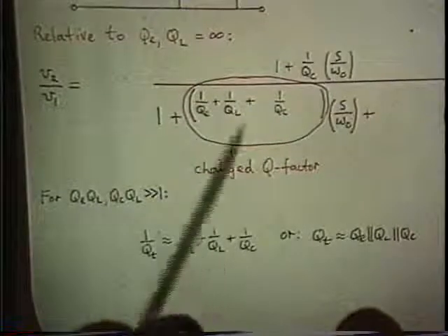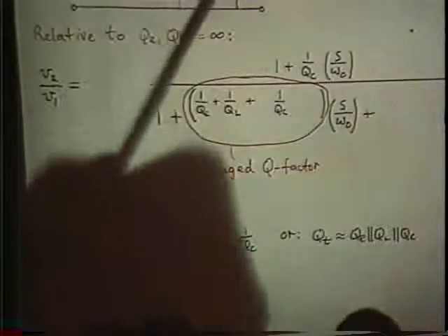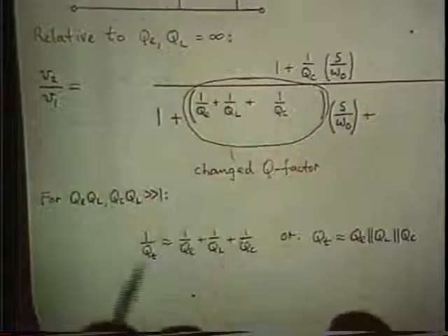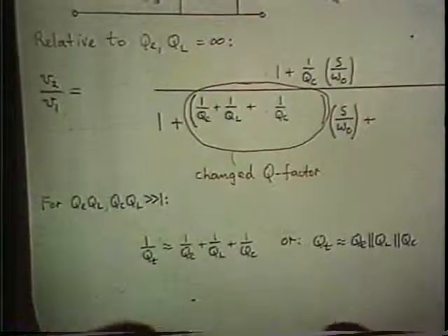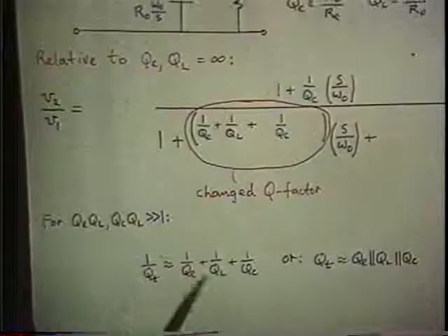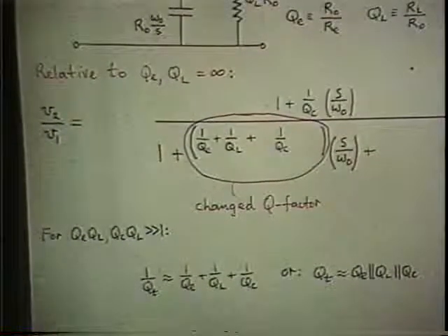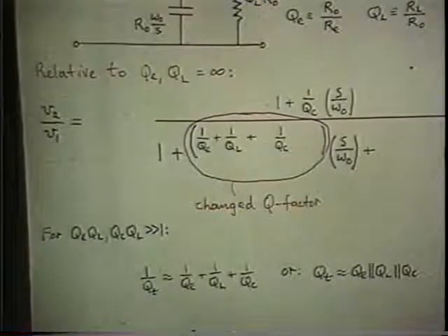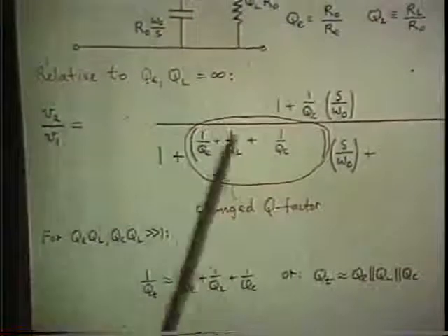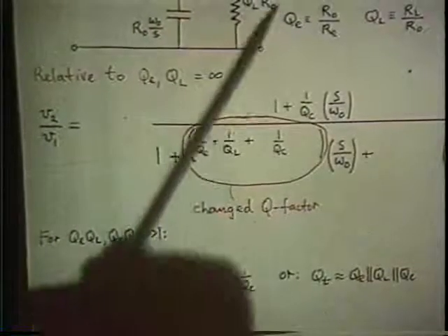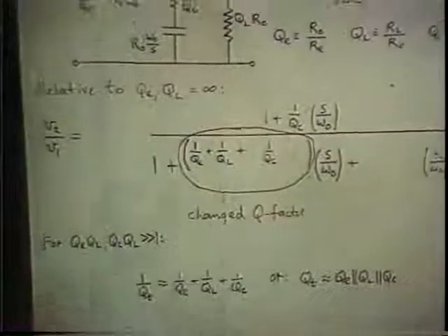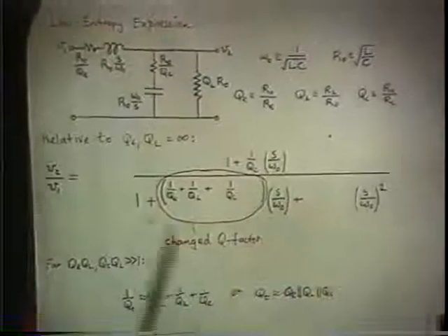It tells you whichever is the most significant damping factor is the smallest one. And the total Q factor will be smaller than the smallest of the 3. And that's useful information for design. In terms of power supplies, for example, the load resistor is independently specified for various other reasons.